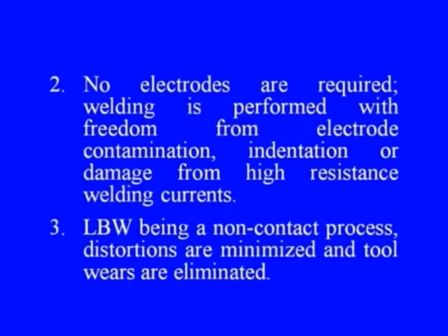Welding is performed with freedom from electrode contamination, indentation or damage from the high resistance welding currents. In fact, there is no current being applied to the workpiece. Only the laser production system needs the power supply, which is different. Laser beam welding being a non-contact process, distortions are minimized and tool wear is eliminated.